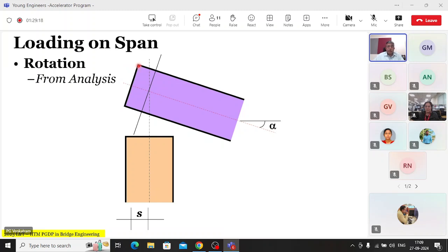because this point is where the road surface is, and at this place, originally when it was having no live load, it was vertical, and when you have a rotation it moves this way and this moves backwards. Okay, or on the other hand, if this doesn't move, this line will have to be shifted here. The CG line of the load acting point will shift, and there will be a small moment also that can come in due to the eccentricity. But there will be a lateral displacement in this direction, and that much can happen in that direction. This is also a consequence of a rotation.